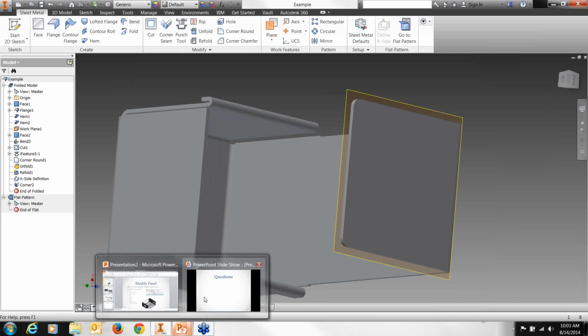Must the added rip be placed on a fold? No. The rip can be across a face at a center point, or if you've got sketch points put in somewhere indicating it, you can apply the rip along those points as well.